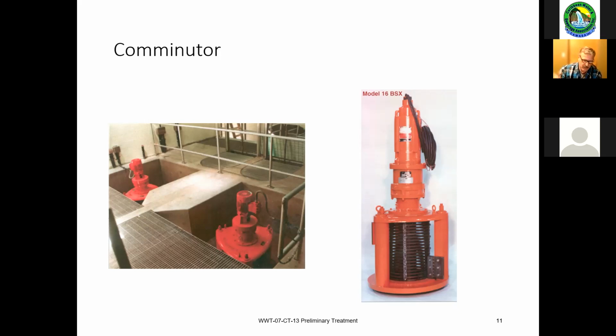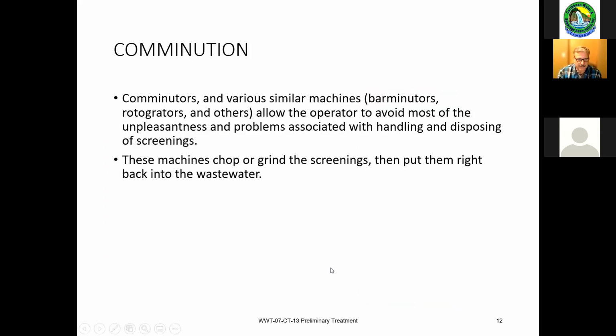Making the pieces smaller, having them flow through the system, and then removing them at the plant works really well. Those grinders do not make the pieces smaller than 10 millimeters, so everything is removed at the plant itself. But it's not preferable to just have grinders in front of a wastewater plant without anything else.